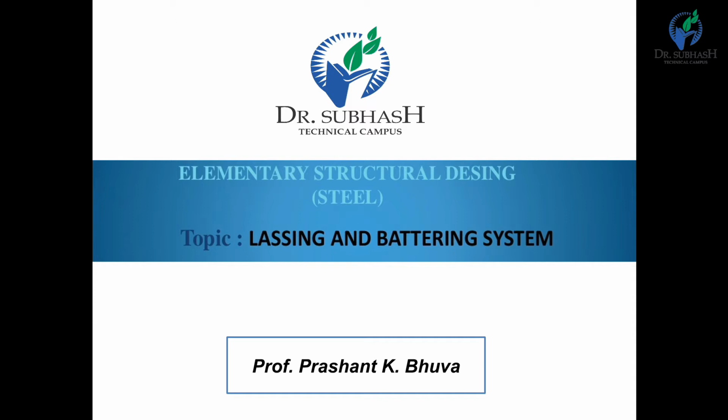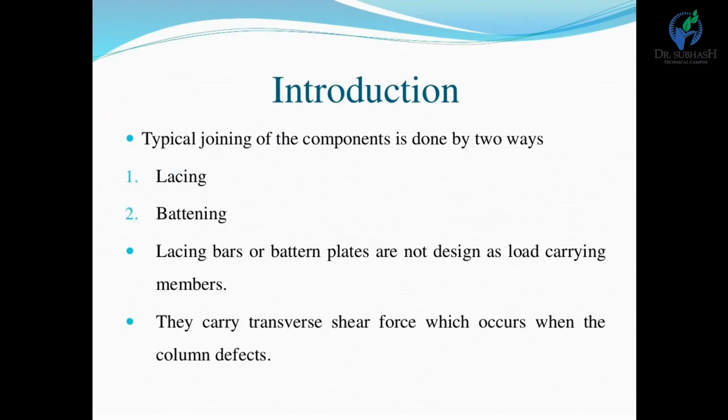So the joining of components is done in two ways, namely lacing and battening. Lacing bars or batten plates are not designed as load-carrying members, but they can carry transverse shear force which occurs when the column bends.